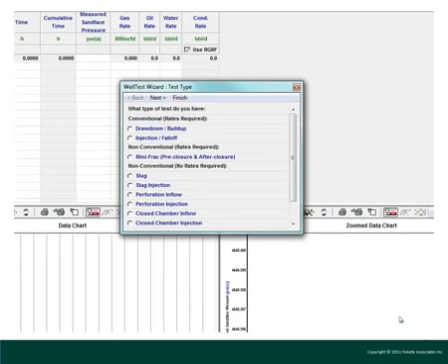Now, along with conventional drawdown and buildup tests available in WellTest, we also have a variety of unconventional test types to choose from. Slug injection, closed chamber inflow, and closed chamber injection, primarily used for offshore DST analysis. Mini-frac and perforation inflow and injection, or PIDA analysis, used for fracture diagnostic analysis.